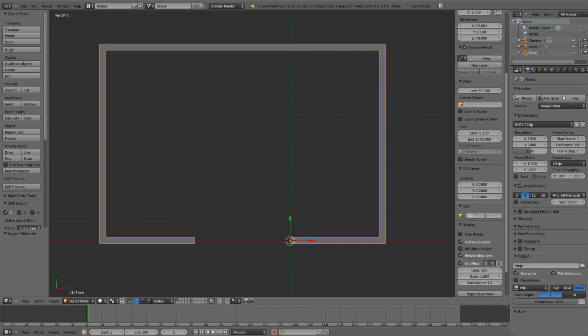So now you can save your Blender file, and I'm going to name it castle.blend. So with the object still selected, go into the left hand side, under where it says origin, hit origin to geometry. This will place the center of the object in the center of where all the geometry is, if that kind of makes sense. We'll be looking into this a little bit more later.